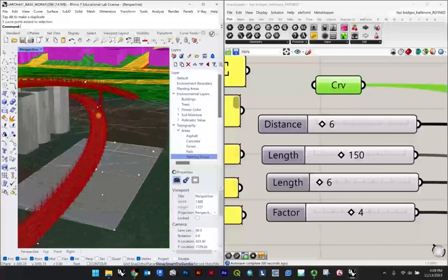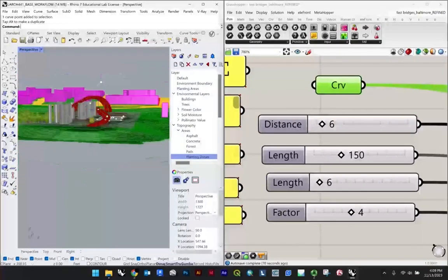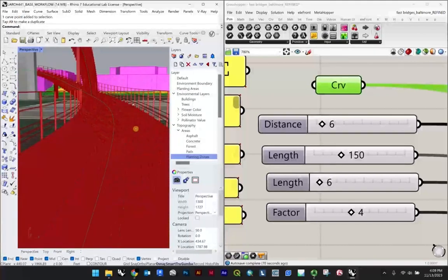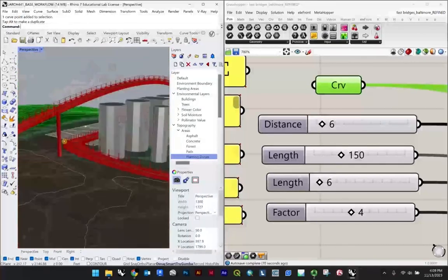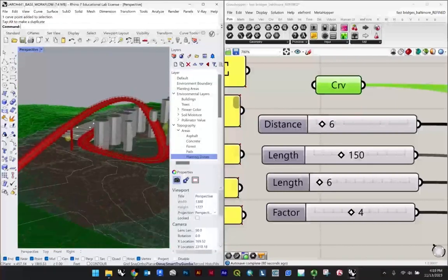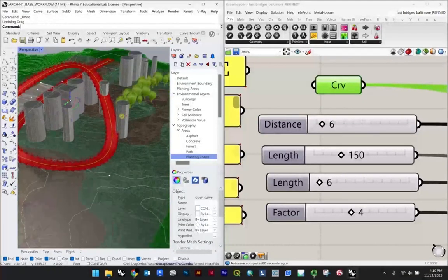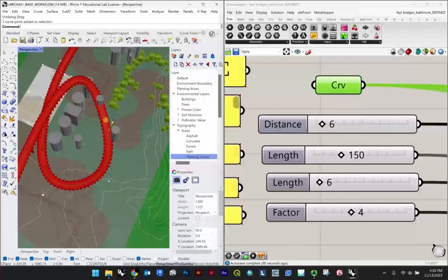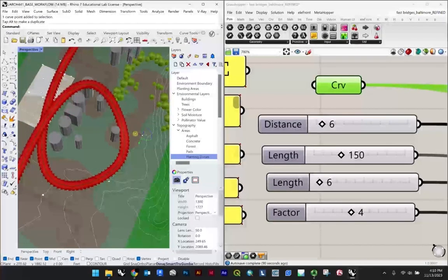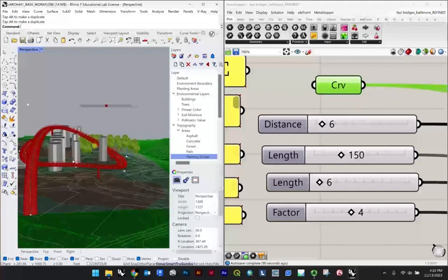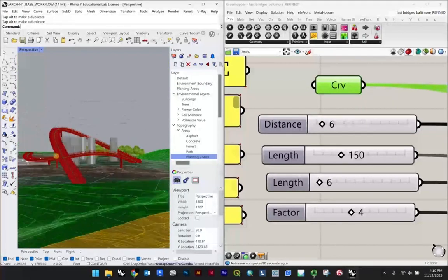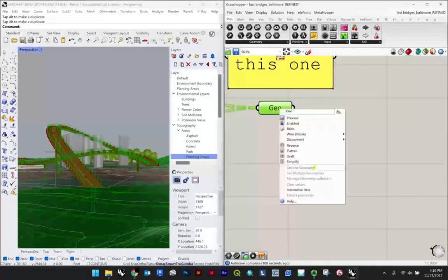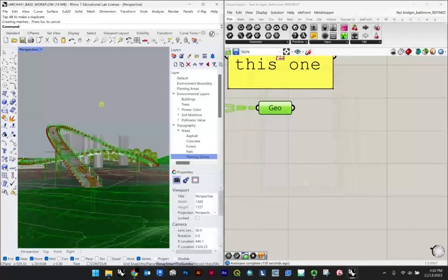So we do have a little collision here. Really great tool, especially if you're doing like boardwalks and things. That's originally why this one was developed, was just to in real time make some quick previews. But you can start to have this in really crazy ways go. You can just modify some of these. So, you know, if we know that that's going to hit and have a collision, just pull on it a little bit. And there, certainly not ADA or anything like that, but this one, to bake it out, just down here, right click, bake. You can do that on contours.